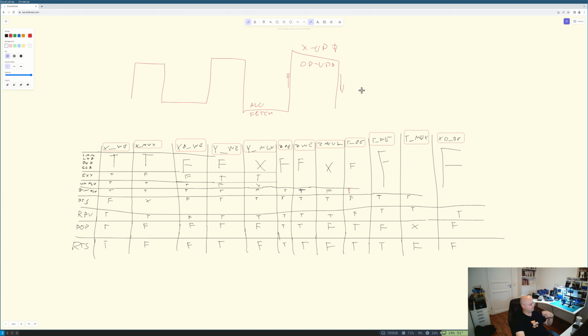And as we are using CMOS logic, the logic that operates on just the positive side of the voltage, so it requires voltage between 0 and some positive value, like plus 5 volts, plus 3.3 volts. We cannot use, for example, a sine wave, because we can make a sine wave with really great rise and fall times, but it's negative, so we have to stay on the positive side.